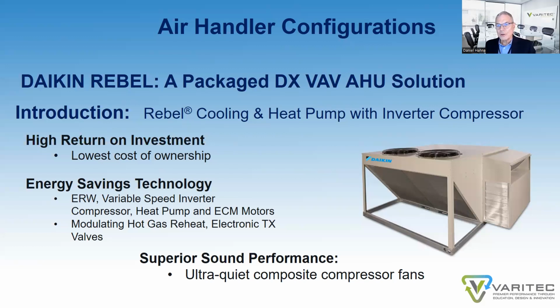Another solution that should be given every consideration is the latest in 100% outside air and also mixed air DX units now. I think Daikin manufactures units up to 75 tons, and these units are excellent for providing proper dehumidification off the cooling coil and using hot gas reheat on the discharge of the unit in order to elevate air off the cooling coil up to the necessary 63, 65 degrees without using supplemental energy.